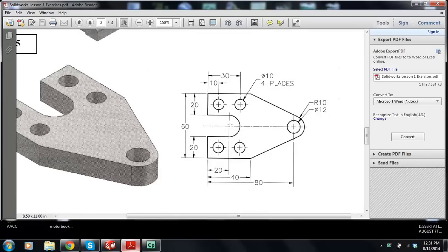My feeling is we need to decide where the origin is in relation to this shape, and you could put it anywhere. You could put it at that point. But the logical place would be either at the center point of this curve or the center of the 2 circles. There's a kind of reason for it. I want to show you these tangent lines later. So we're going to start right there. That's where our origin is going to be, and I'm going to draw a full circle.